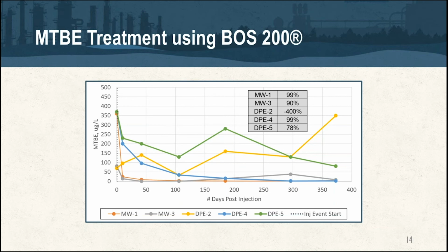So what happens on a site where you have MTBE? The guidance that we give is that if you've got significant TPH mass, specifically the substituted rings like xylenes or toluene, those are going to preferentially sorb and preferentially be treated over MTBE. So if you've got a lot of MTBE and a lot of BTEX, you're going to deal with some of that MTBE.